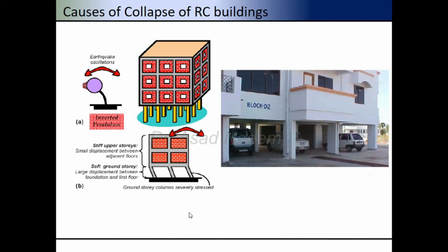This slide shows the soft story building. There are no infill walls at this ground floor level, and there is a huge mass on top of these columns only. And when an earthquake comes, due to this mass, higher inertia can cause the collapse of these columns, and then it can cause the collapse of the whole structure.